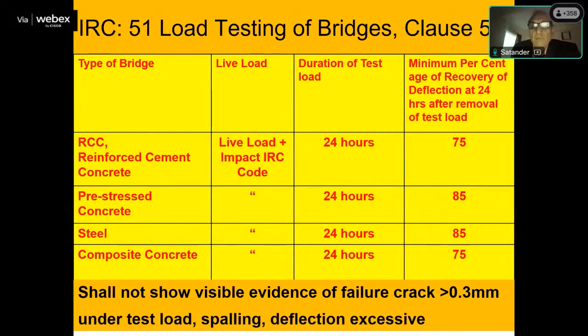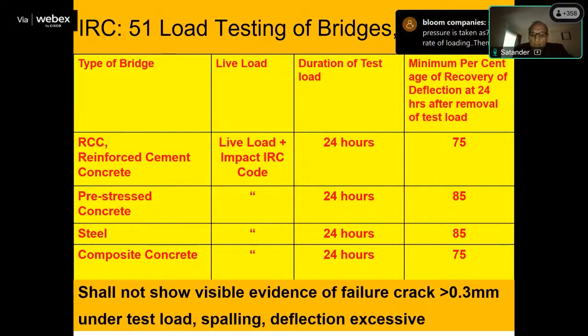Suppose this is for 70R UDL, this is for 80R UDL; that is the IRC SP 37 code. The most important part when testing: suppose you apply the live load plus impact load, whatever loading is given, for 24 hours. Suppose it deflects 10 mm. When you remove the load, after 24 hours, you take the reading, 7.5 mm, it must recover back.